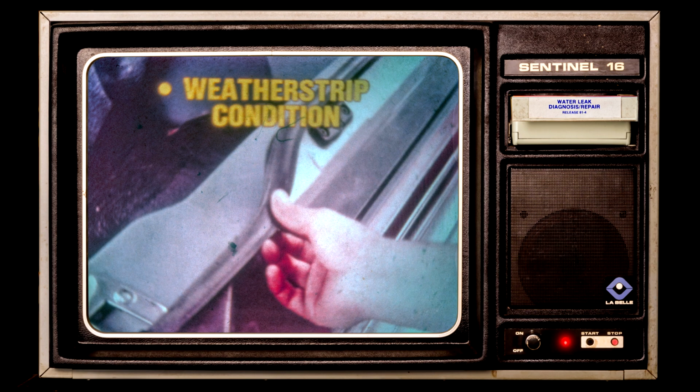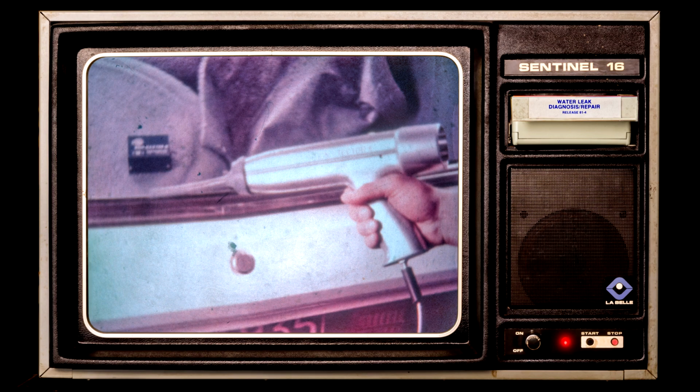The weather strip should also be inspected. This one's intact, and there's no gaps evident between the weather strip and the body. At this point, we've completed the visual inspection step. On leaks of this type, the light test wouldn't be effective. However, an ultrasonic test can be helpful. If you have access to a listener tool, perform an ultrasonic test at this point.